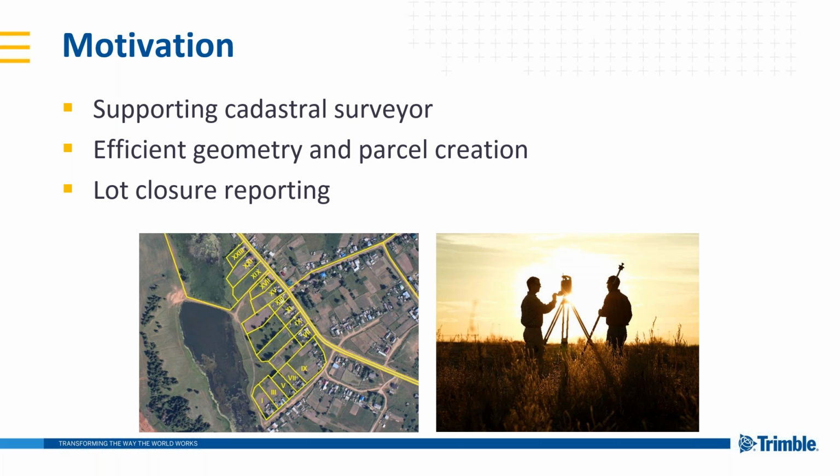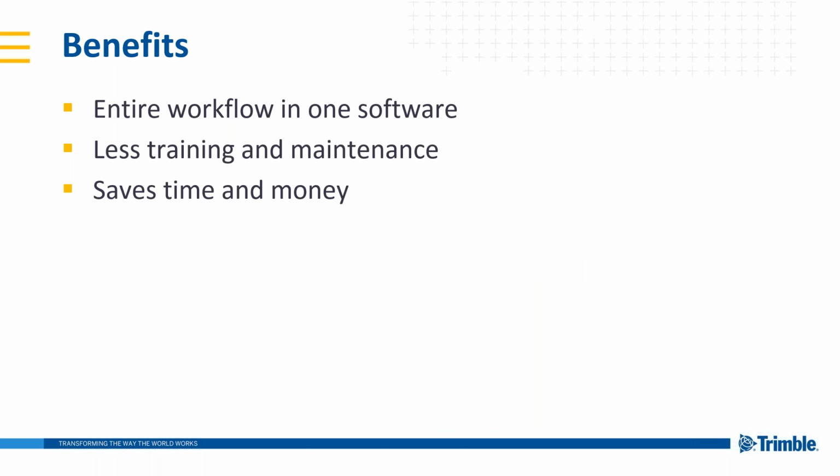So continuing on, the motivation. Like I said, back to our roots, supporting the surveyor in all of their workflows. There's been a lot of effort put on point clouds and working with point cloud data in TBC, but we want to step back and show you that there are a lot of tools going back to that conventional cadastral survey workflow. Through that, we've created a command called Create COGO. With that, we've enabled efficient geometry and parcel creation using a hybrid of mouse and keyboard input. The idea behind this was to satisfy those users who are used to AutoCAD-like input with the command line and things like that.